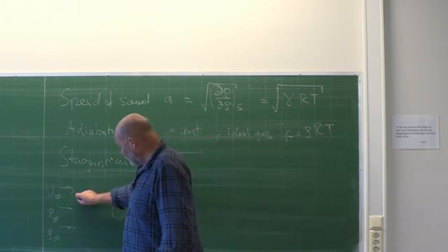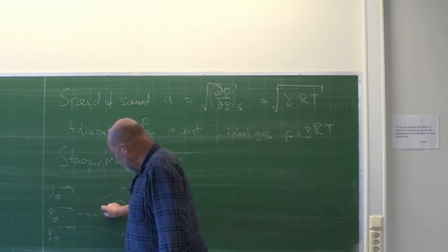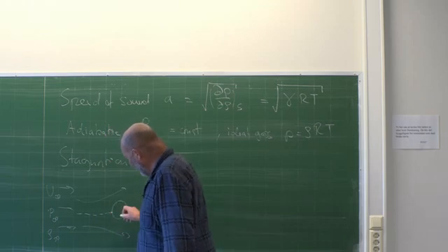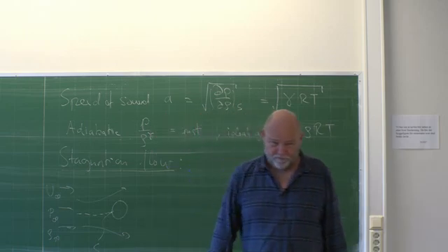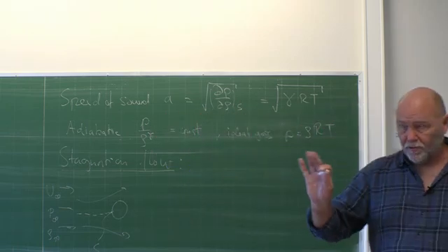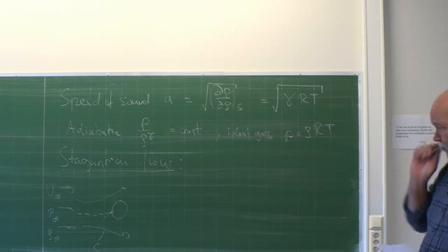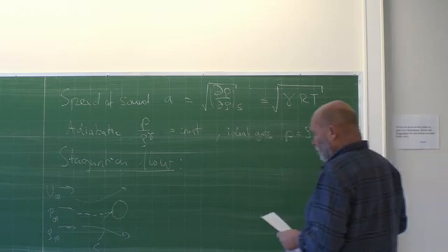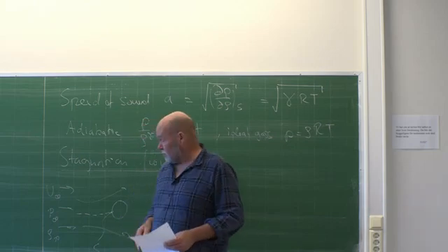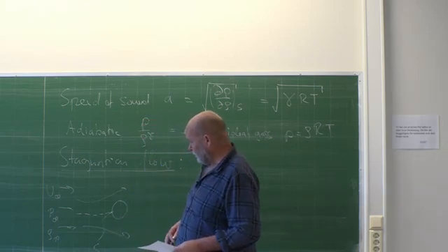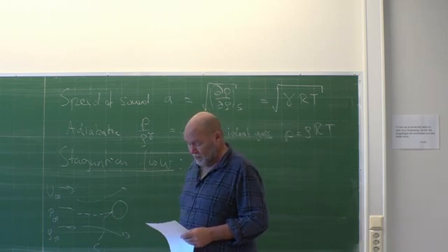And then, of course, the streamlines will go around this one, but we'll have one streamline hitting the exact stagnation point, S. So you compare these two points, and when you're now using the Bernoulli equation, you do it simple. We neglect gravity, we neglect friction forces, they're not important here.